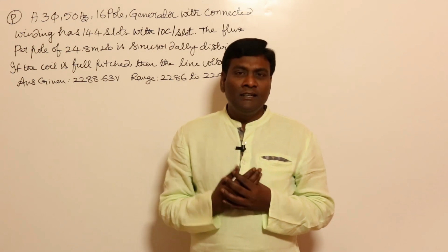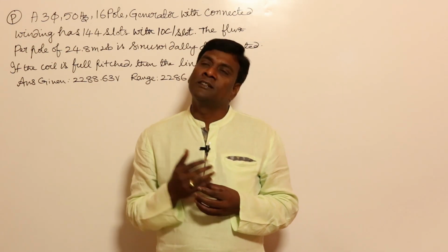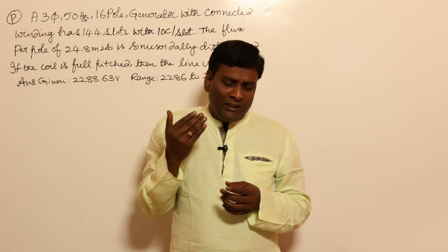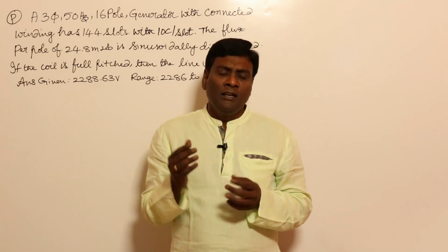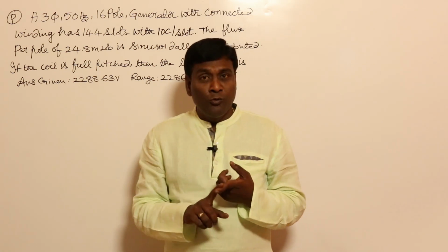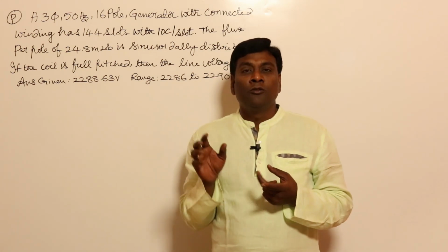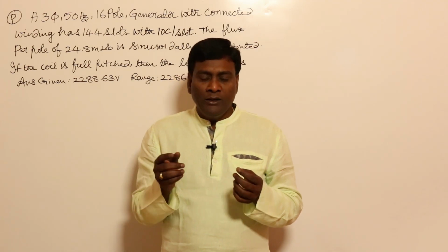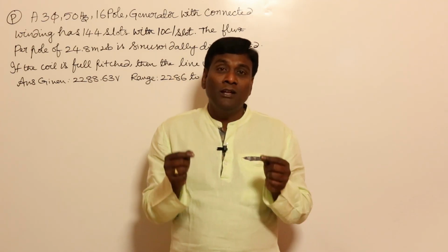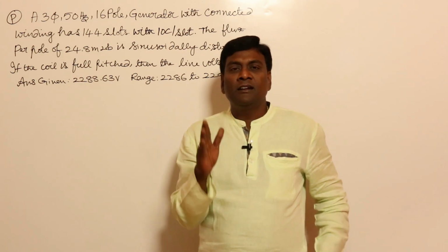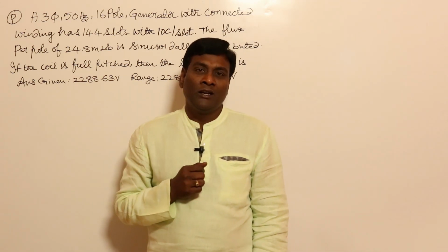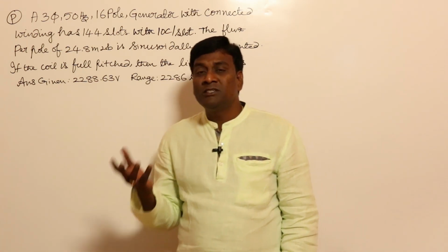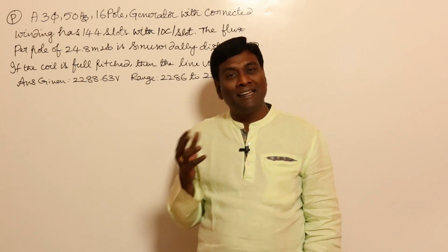Recently, when I launched some videos on synchronous machines and induction machines, I got some friction, because somehow faculties were saying 50 Hz is completely fixed, and for a 2-pole machine the synchronous speed should be 3000, for a 4-pole machine it should be 1500, for a 6-pole machine it should be 1000 rpm. By repeating all these, people are feeling that 1500 is the synchronous speed and it should not reduce. If it reduces, because they are kids, they connect it to maybe stability, or to something else in transient analysis.